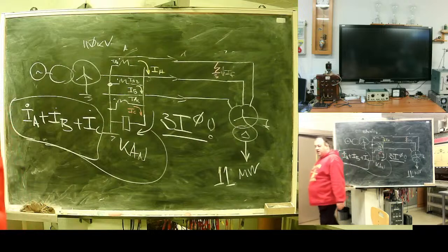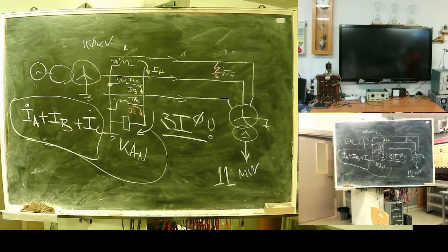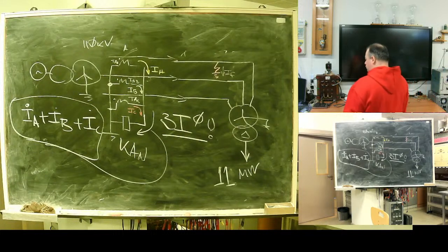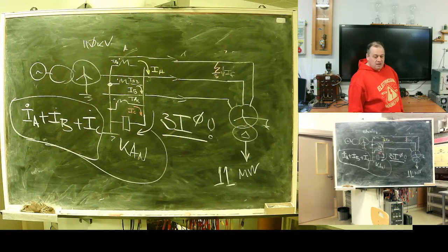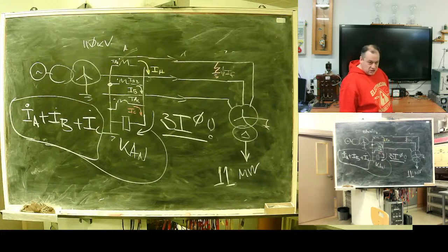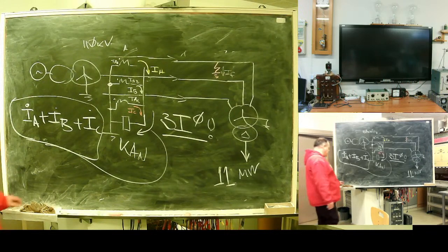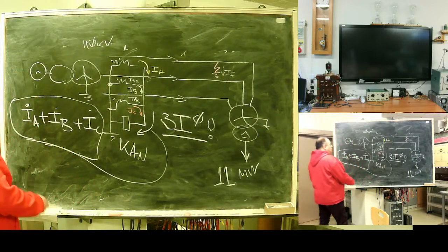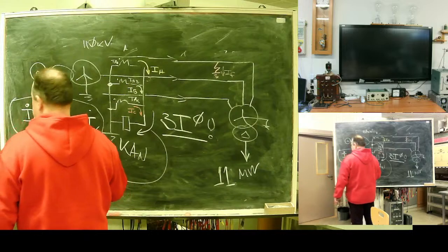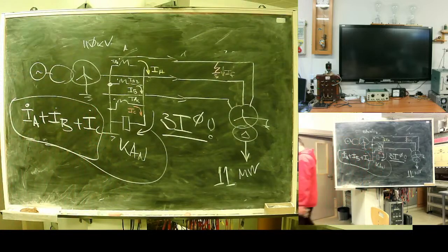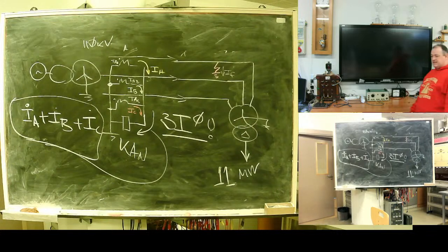What's interesting here? We have no signal in load regime, zero signal, and full fault current in case of fault regime. This means what? That we can get very sensitive and robust protection. So Earth fault protection relies on zero sequence current, and it's highly sensitive.